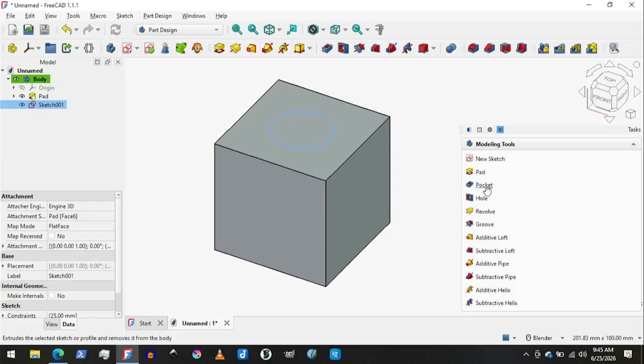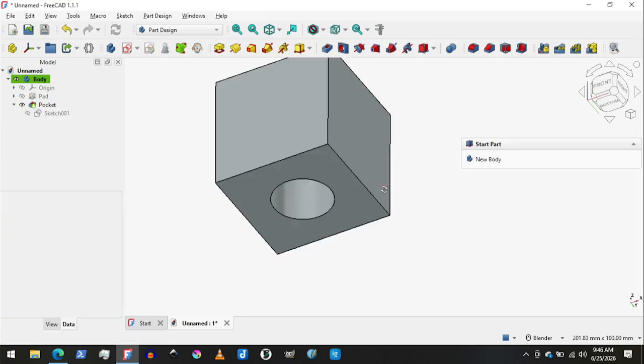The problem is they're solid, which means they're actual lines. So I'm going to undo that, and I'm going to click construction, and what this does now, when I click GX, is it creates dashed lines. That means they are there as far as the computer is concerned. The computer sees them, you can see them, but when you go to actually make the shape, you won't see them. And so we can use them for calculations, we can use them for our equations.